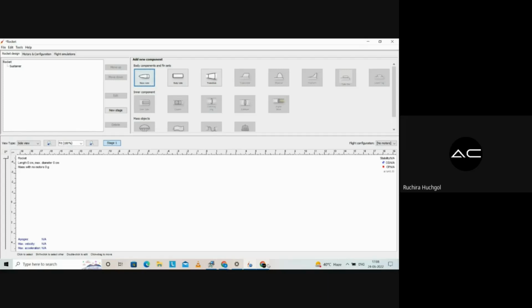Then there are a number of shapes of nose cones that have been used, like the conic, blunt conic, double conic, elliptical, as well as parabolic. But the very common one that we use for our competition, or even for general purpose for model rocketry or experimental rocketry, is the ogive cone. It is used because it is the most common, easy to manufacture, and cost effective, as students are making this particular rocket. So the most commonly used nose cone in model rocketry is the ogive cone.